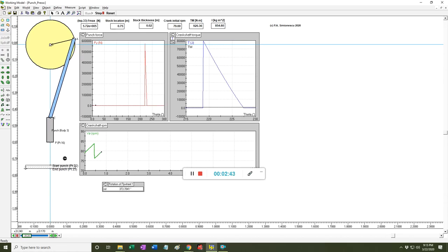Okay. Regarding the simulation, if you correctly calculated the average torque, then this zigzagging line in green, this is the velocity of the flywheel. It's going to remain zigzagging, yes, but will remain horizontal. Otherwise, with too small an average torque, the zigzagging will go down. If you apply too big an average torque to the motor, the zigzagging will move up.